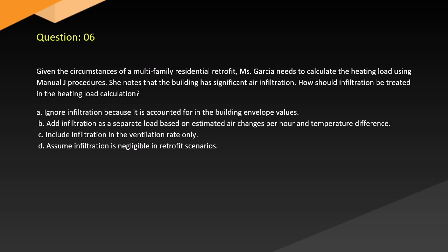A. Ignore infiltration because it is accounted for in the building envelope values. B. Add infiltration as a separate load based on estimated air changes per hour and temperature difference. C. Include infiltration in the ventilation rate only. D. Assume infiltration is negligible in retrofit scenarios.